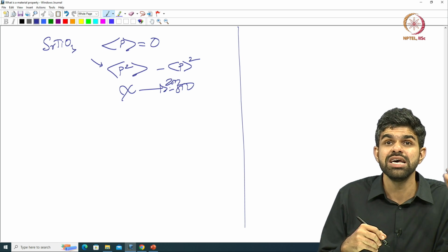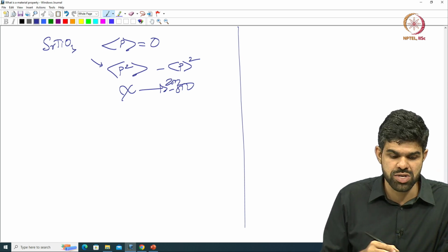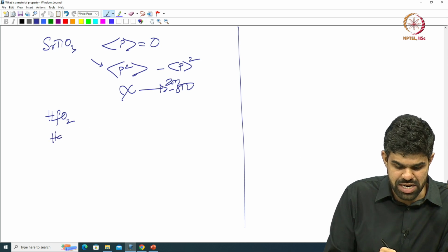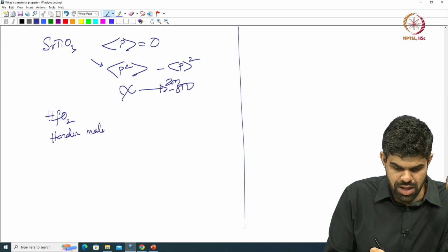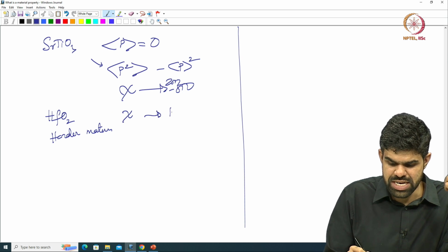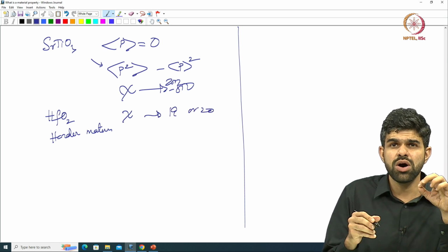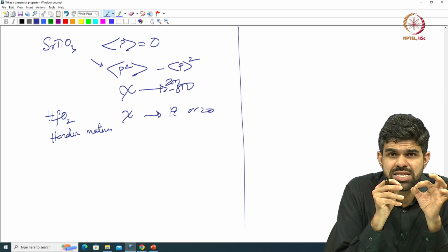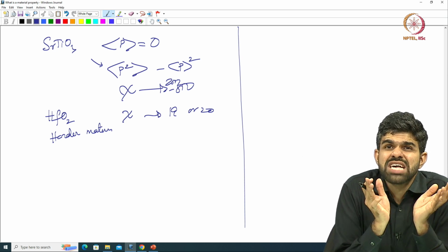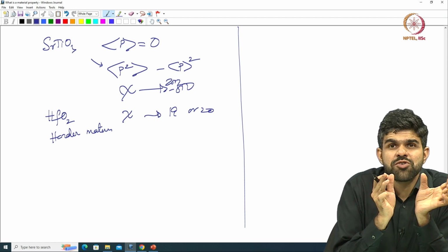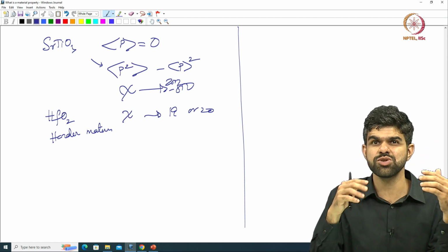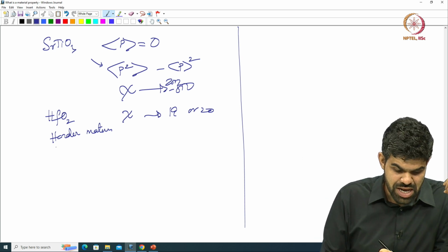So this is a high susceptibility or high dielectric constant material, whereas if I take something like hafnium oxide, this is a harder material, where the dielectric constant or susceptibility is only 19 or 20. Although I can create these microscopic polarizations, they do not fluctuate. So it is harder for any configuration to change to follow the electric field. This is a much harder material.